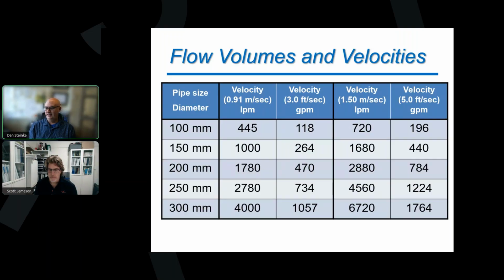Samuel would like to know, what are your suggestions for achieving the proper velocity in large diameter pipes? For large diameter mains, well, then you're looking at maybe doing flushing from both ports out of a hydrant, possibly doing it out of the 4-inch port of the hydrant. And if you're going really large, well, you might have to open up multiple hydrants and get that flow up.